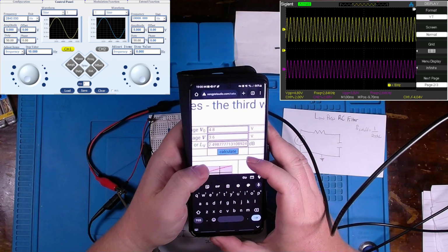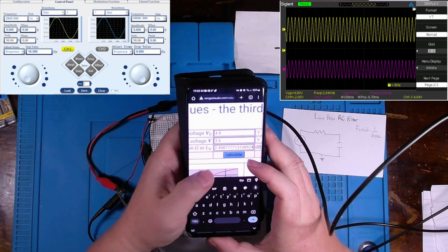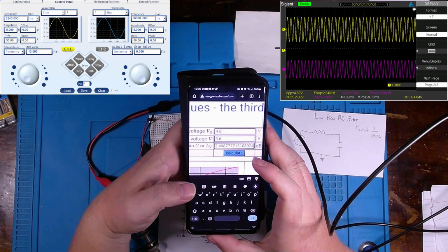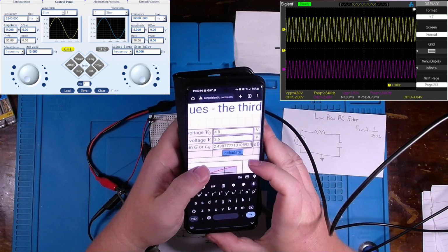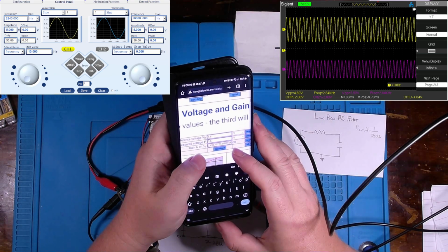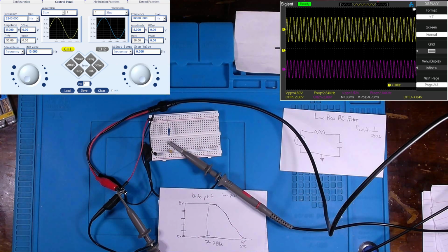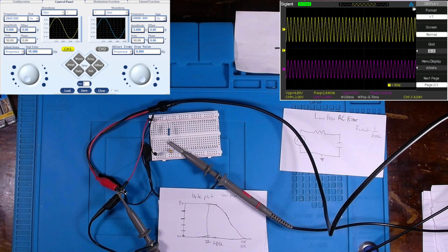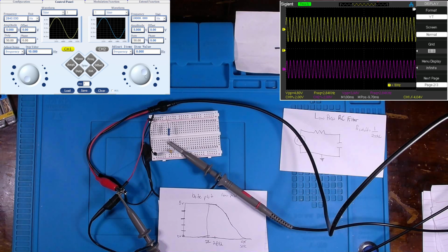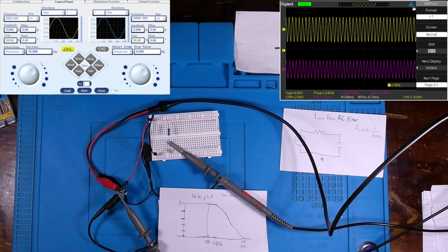You can see here with a reference voltage of 4.8 on channel 1, and we're now getting around 3.6 volts. That's almost 2.5 dB of loss right there once we're at the point where we need to start attenuating. And then we're going to attenuate even more significantly as we start to increase from that point.